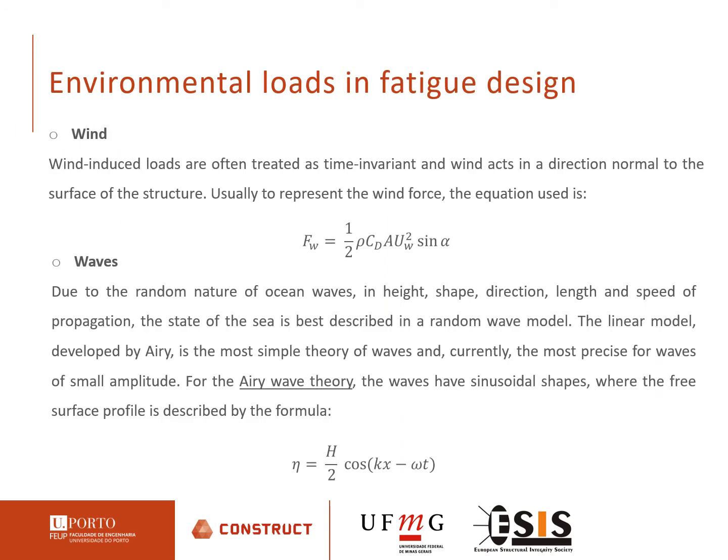The design of offshore structures is based on the conditions and the environmental aspects to which the structure is submitted. For the static analysis, an offshore structure can be submitted to permanent loads such as dead weight and equipment, gravity loads, live loads, and hydrostatic loads. Dynamic loads are generally originated by environmental loads: wind loads, wave loads, current loads, ice loads, and other environmental loads.